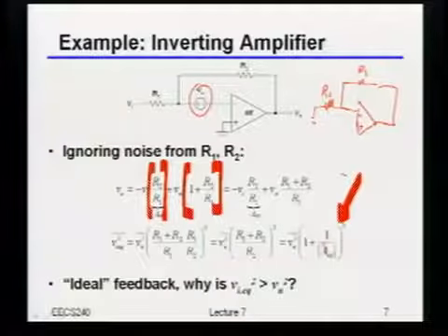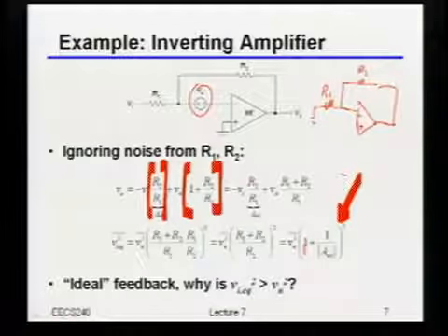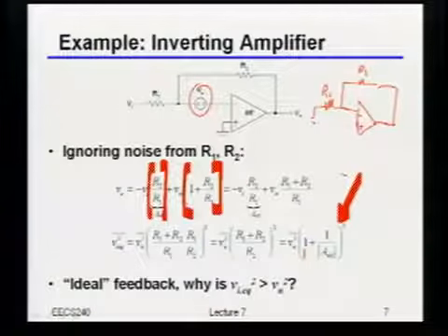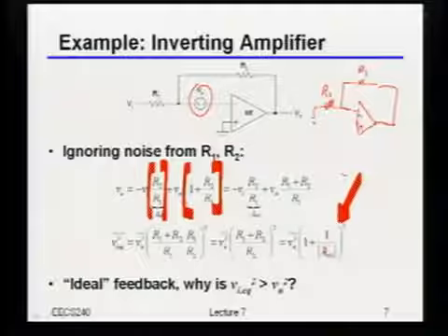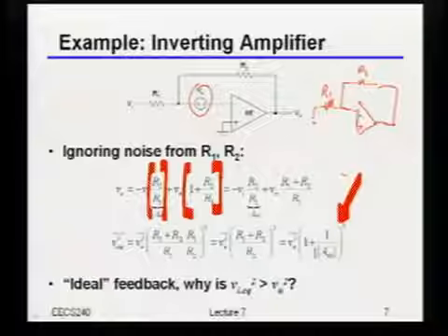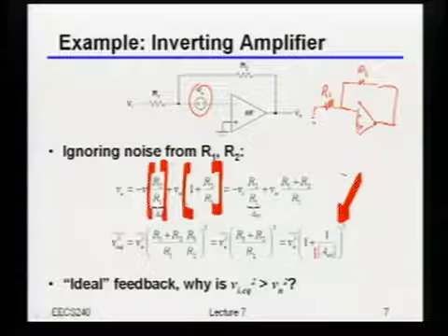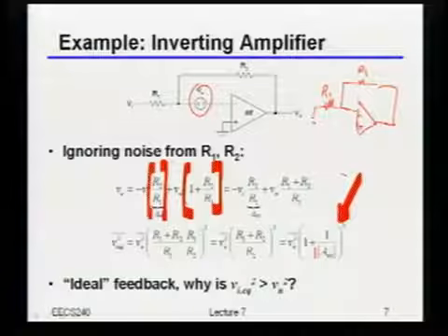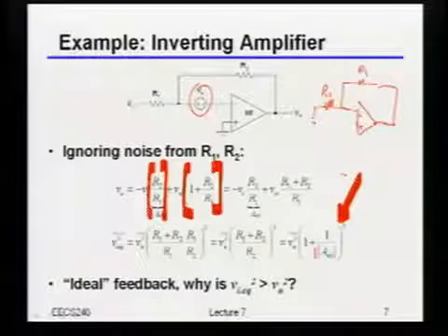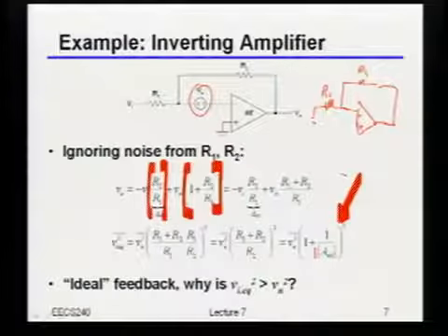As an example, if I use the gain of 1, I would actually be quadrupling the noise variance. If I use the gain of, let's say, 2, it's not quite as bad. It's 1.5 squared, right? But clearly, this factor right here is greater than 1. Okay? So now, here's the question to you guys. I had no noise whatsoever from the resistors. So how in the heck is it that by tying the op amp up like this, I've actually increased its input equivalent noise? What happened there?